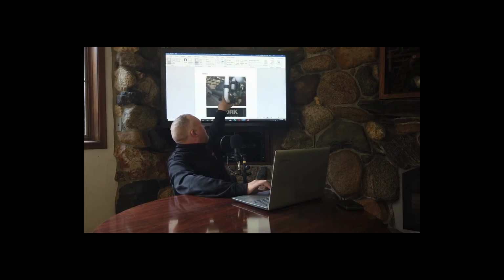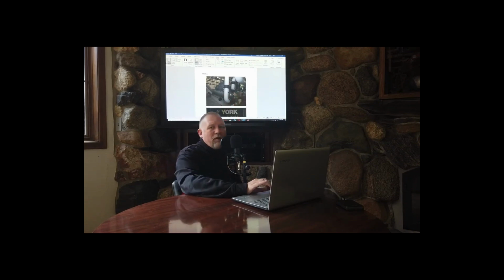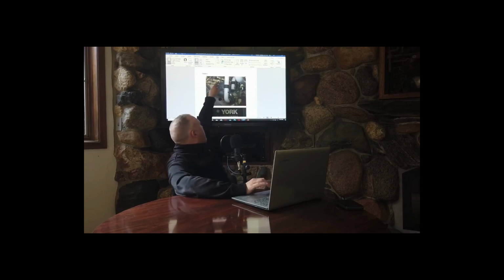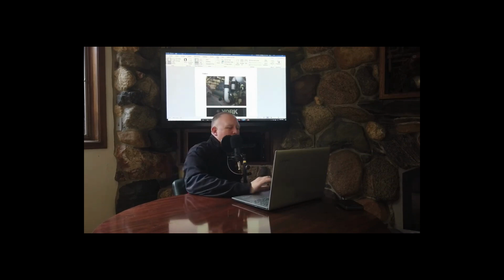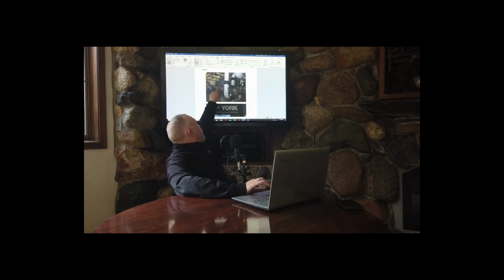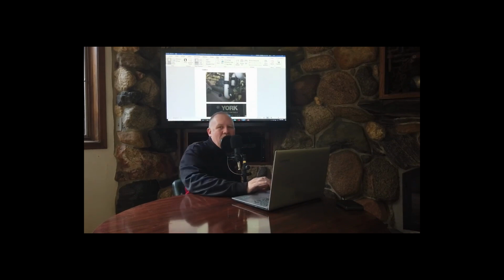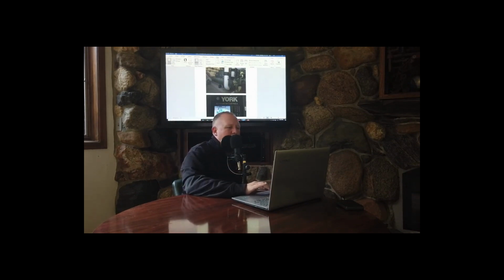All right. This is a water-cooled chiller. See these circular parts? One of them is the evaporator barrel. One of them is the condenser barrel. The part on top is the compressor. That's also where the thermal expansion device, or rather the orifice for a big machine, is going to be. This big flat panel here, that's the power input to the compressor. On a very large one, we'll have that variable frequency drive on it.